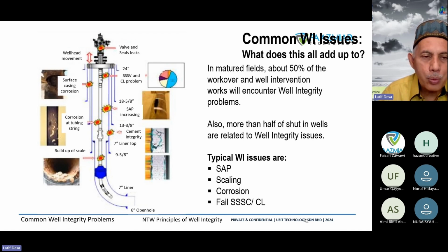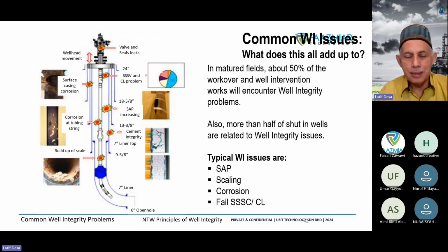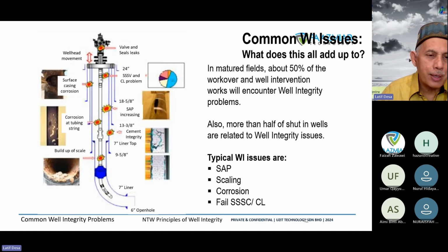We are not really planning the well to handle this issue. This is what is going to happen. With multiple failures, you have to shut down the well and do a repair job. A repair job means that we have to go in, fill the well, and pull up the tubing, then investigate the casing to see whether the thickness is still there. If the thickness is not there, we're going to run another casing to case off this area, and run a smaller tubing and complete the well with something smaller, because of the requirement to set another casing to seal off the leak in what we call the production casing.